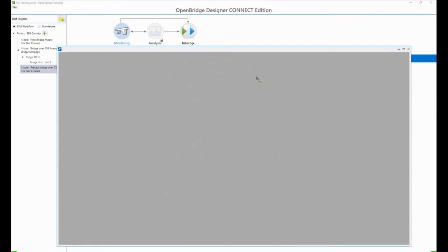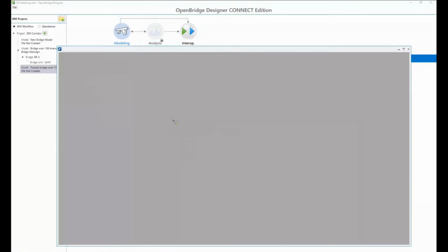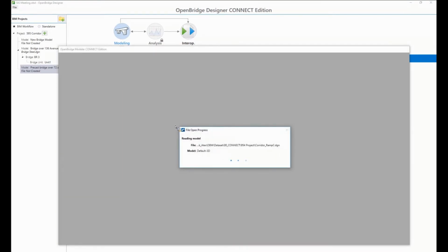Right? This is a quick one. Is there a version of LEAP that allows British standards and Eurocodes? I'm sorry, Liam, no. The only option to design now with the Eurocode or British codes is sending your design, like this precast bridge that I'm loading, to RM Bridge. That's going to be the one doing that, with design codes that include the Eurocode, the British code, and other ones too.